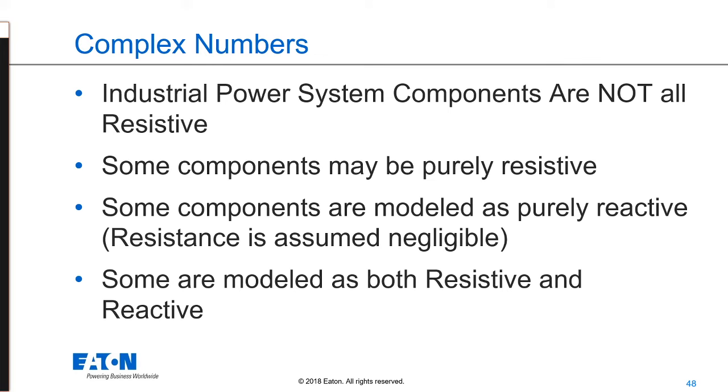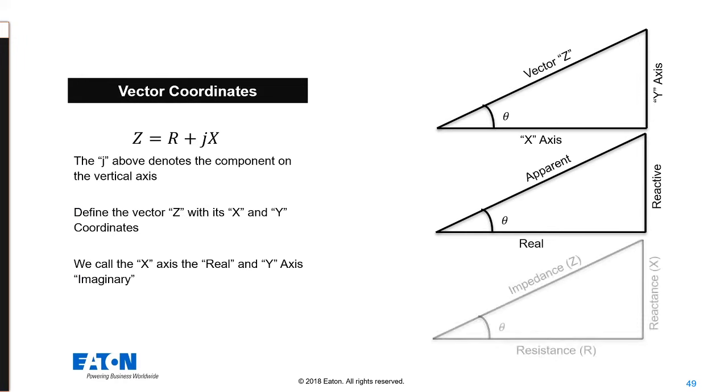or maybe a reactance and a resistance. Basically what we're doing is creating what we call the power triangle. If you're familiar with the power triangle, you have real power across the bottom, reactive power up the side, and then you have your apparent power. So you have watts across the bottom, VARs up the y-axis, and VA across the hypotenuse of that triangle. The angle of that triangle is your power factor. I'm planning to do a web event just on complex variables, just on this power triangle, to help us understand the power of that.